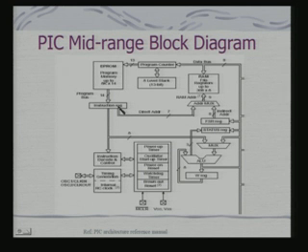This instruction register typically will have the instruction, and it will refer to the registers for operation. So, that is why you find a bus connecting this part of your instruction register to the address multiplexer through which the register gets selected for any kind of arithmetic operation. Okay. So, from this register the data would flow onto the data bus, and then it will go into this multiplexer so that it can be used in the ALU for various operations.